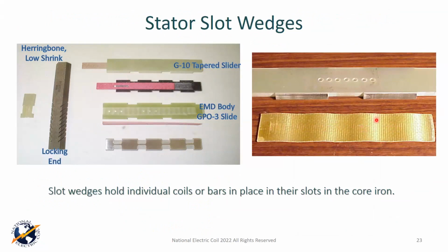Now, from a maintenance standpoint, I'm not positive, but I believe Westinghouse is one of the ones that introduced it, but you see these holes that are in the wedge here, and you look at the ripples in that filler. You have to imagine this is a way to check the wedge tightness by gauging the deflection, or how flat you have this, or how much it's sprung loose, of this top ripple. And so you're using a very tiny diameter pin mic to get down here and mic each one of these holes.